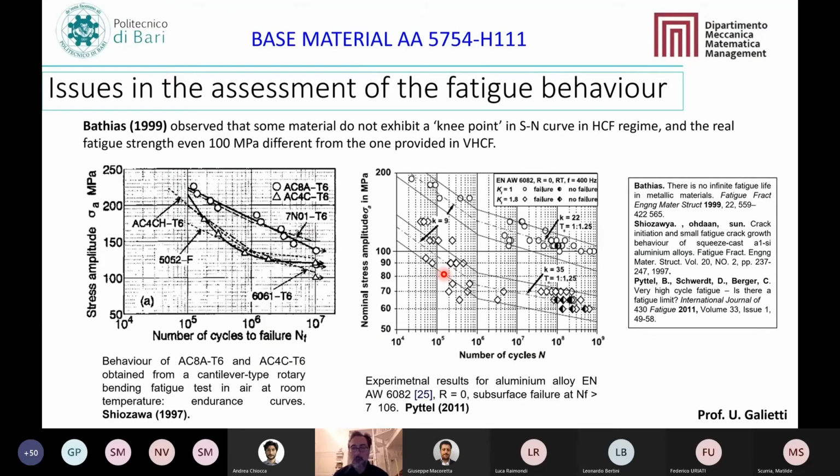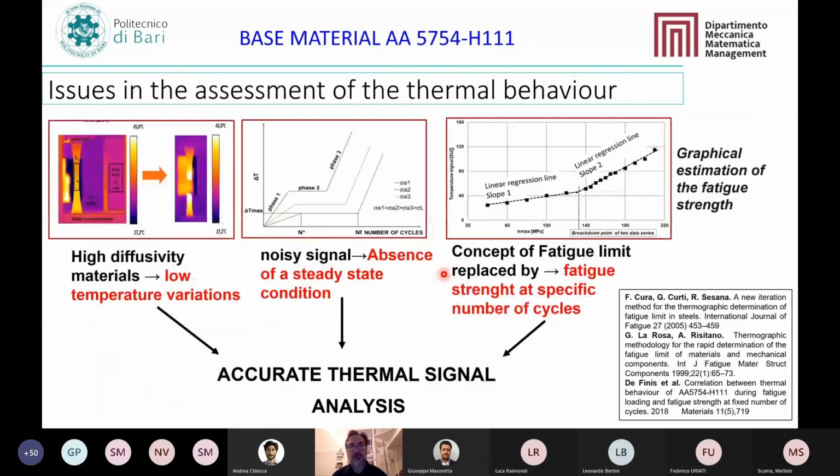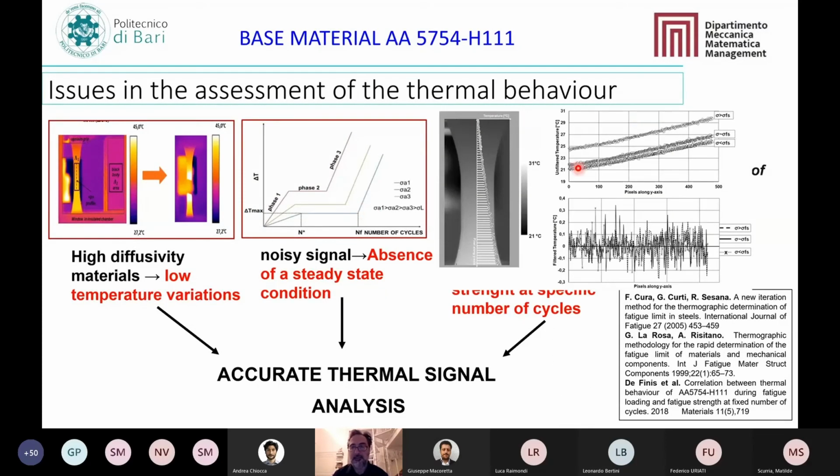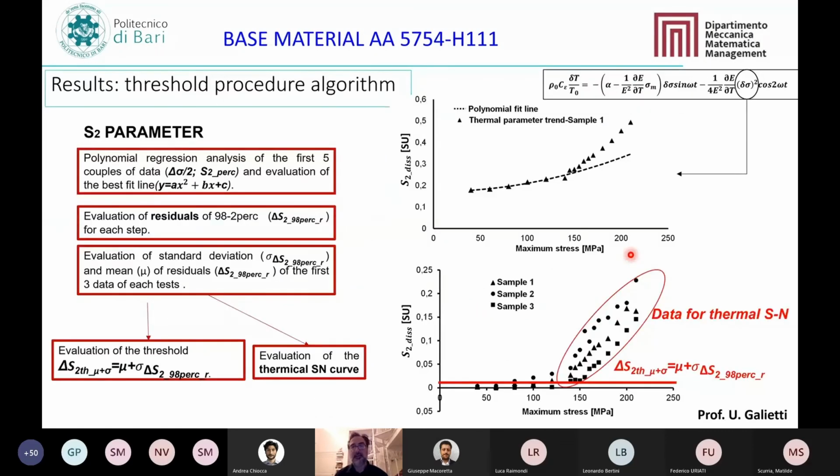If we want, but I mean, that was easy. It's much worse for aluminium, because aluminium actually, yes, it should work like that. But this is the temperature change during a block of 20 cycles. You can see that there is no mean temperature change. There's nothing actually that we can measure inside. So the only way to analyze the data was just with thermoelastic analysis.